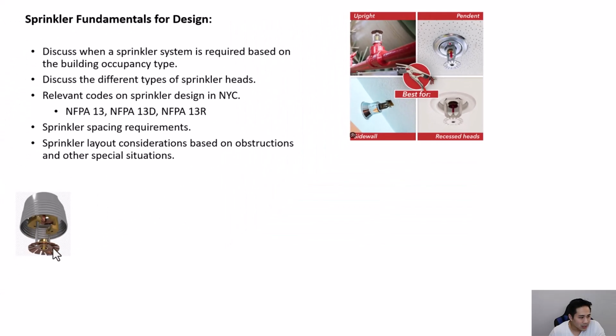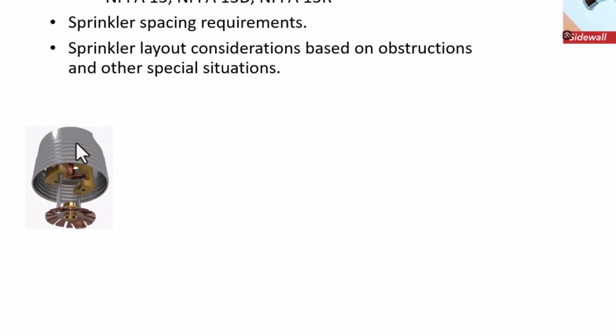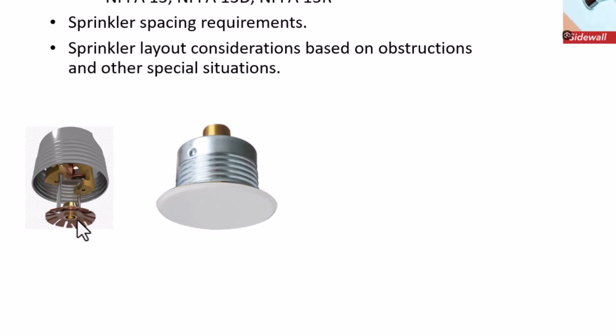So this is what a concealed pendant looks like. This part would go above the ceiling, and this deflector could actually be pushed in and out. If somebody pushes this up with their thumb, it'll slide up into the cylinder here, and then when they release it, by gravity the pendant will fall into this position.